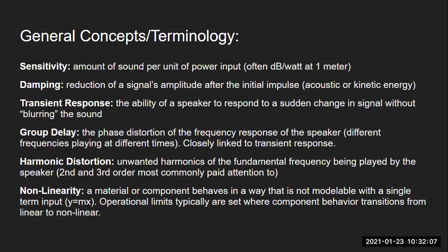So what I mean by second and third order here is that there's even and odd order distortion, and typically second and third order are the loudest after the fundamental, so those are the ones that a lot of people pay attention to when they're trying to reduce harmonic distortion. But sometimes it's fourth, fifth, sometimes seventh order distortion that needs to be paid attention to as well.